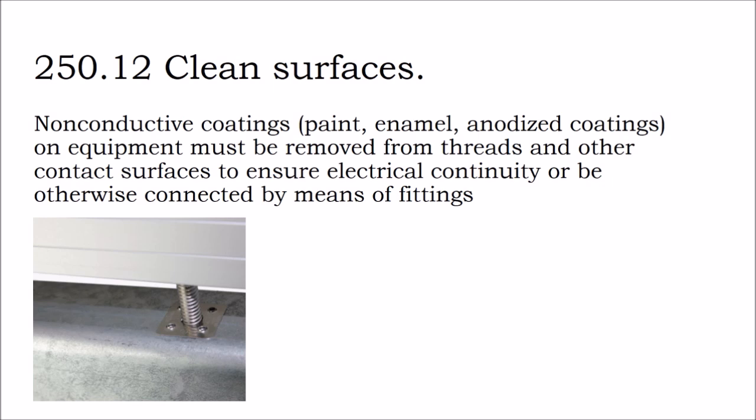I've heard this is an issue sometimes with some brand new SMA inverters that come pre-wired. Maybe the installer didn't note that there was a little enamel that needed to be rubbed off the end of the wires. That would be causing a circuit not to energize, or an arc fault or something like that at the point of connection.